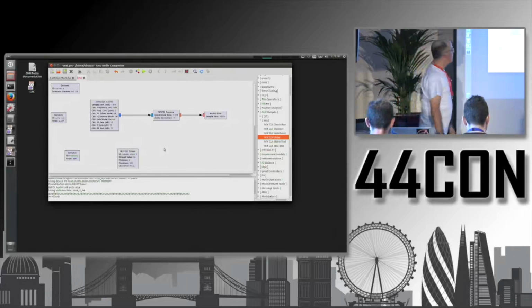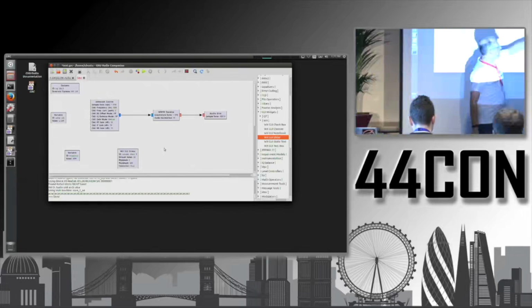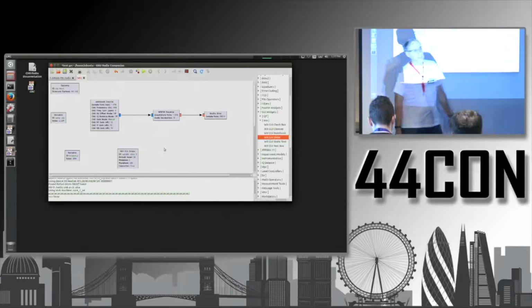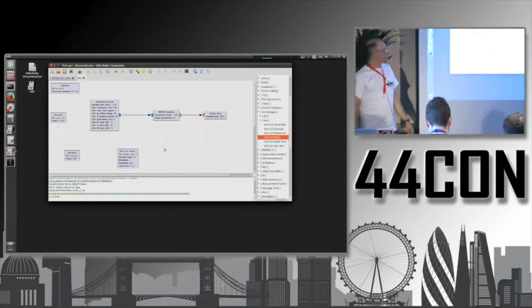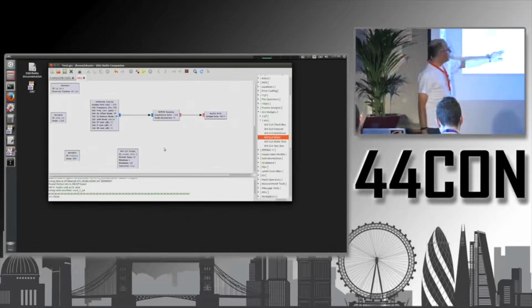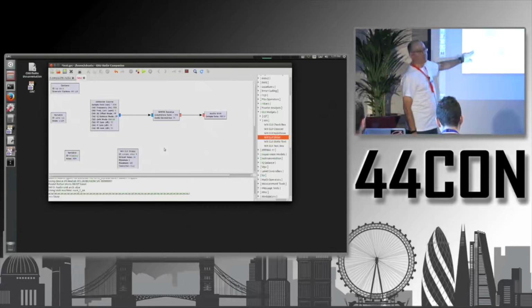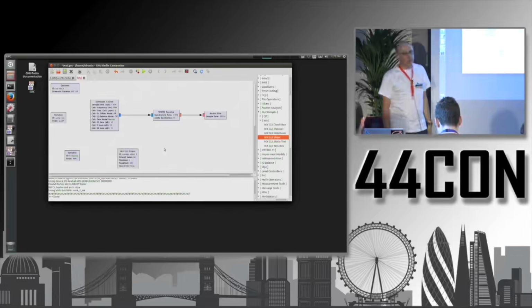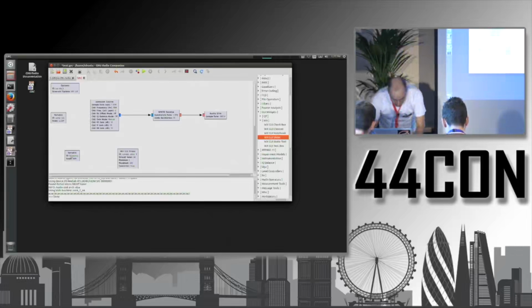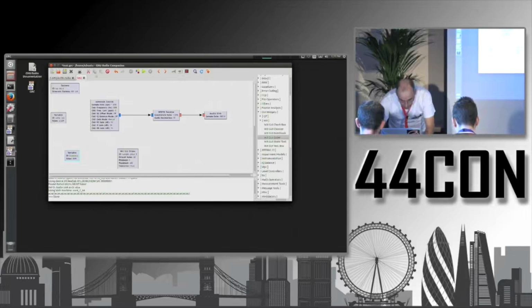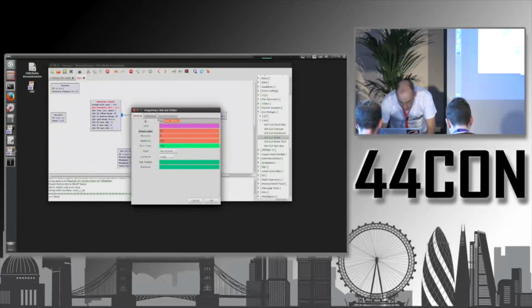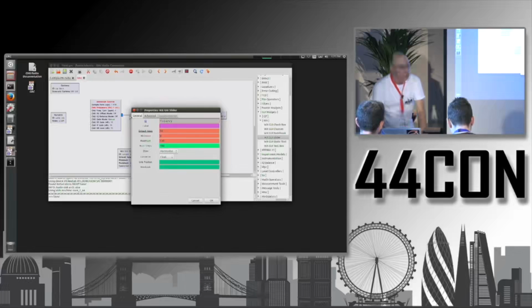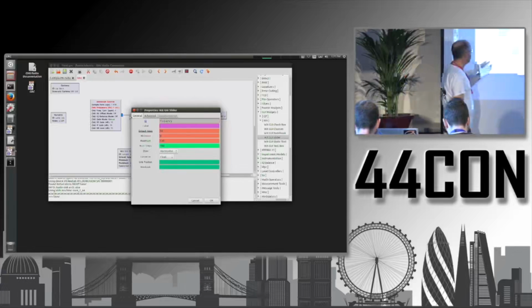Yeah, so under GUI widgets, WX GUI slider. And this one here will replace our frequency variable. So we can delete this variable like this, and then you double click the slider, and you say now that the slider name here, sorry, is frequency. So that defines a frequency.